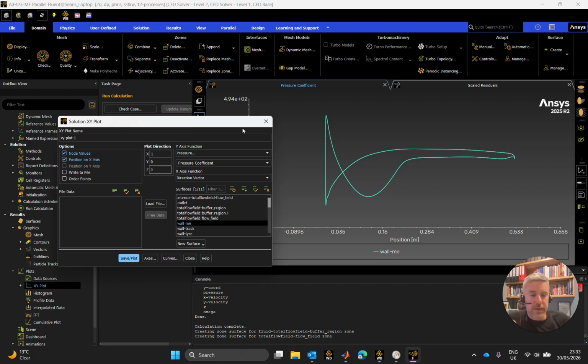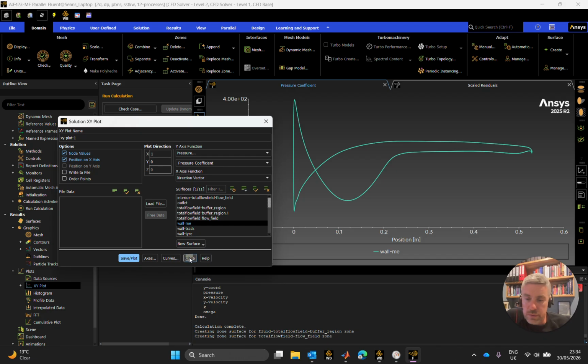And indeed, I'd like to compare this against a Selig Donovan SD7055 main element and see how that's treated. It's less aggressive as far as camber goes, and it might be more suitable for a main element, just to initially treat the flow, accelerate it under the front wing, under the main element, and let the flaps take it over from there, treat the air at its trailing edge, and every subsequent trailing edge after. So a couple of things there to look at. So save that and close.